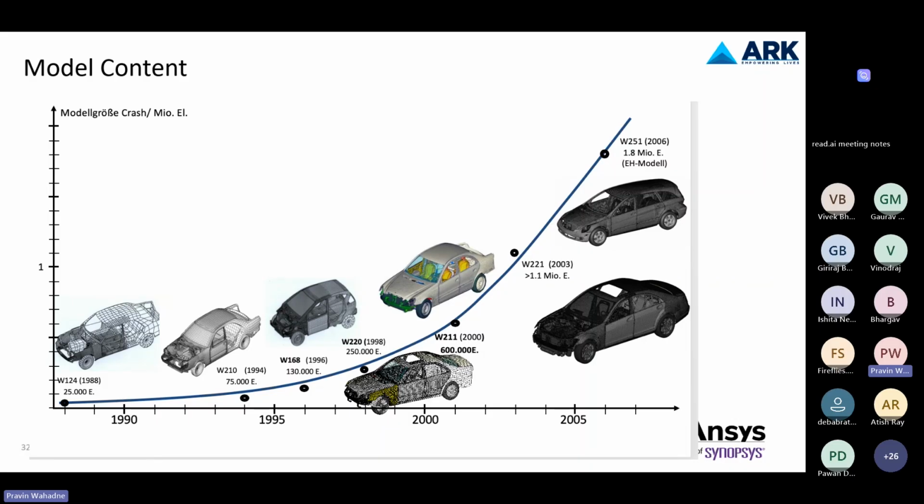Today we can use multiple computers to analyze the entire vehicle. We can use double precision and single precision techniques, and SMP and MPP techniques to discretize the model across different computers and solve it under one roof.